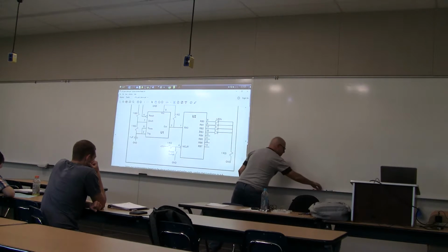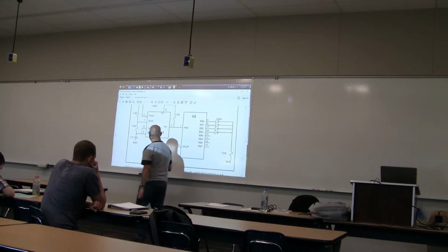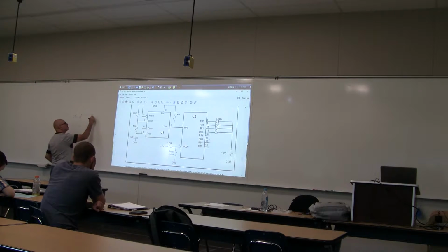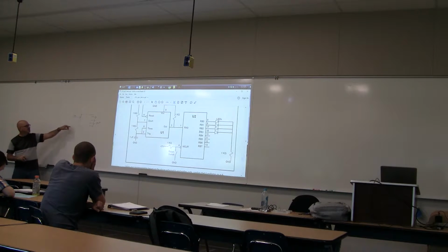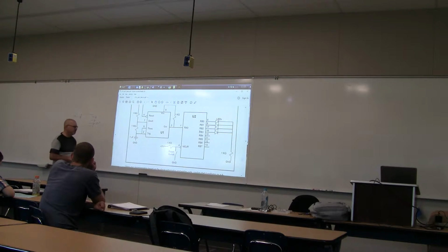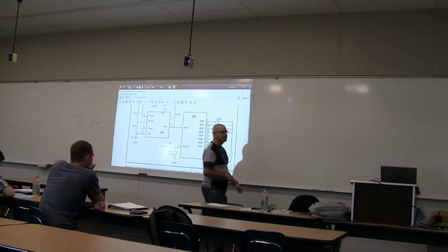So what does this circuit look like? Right, really simple system diagram. 1 input, 4 output lines. And each time that this changes either high or low, the value of this 4-bit output should increase. When it gets to all 1s and you tick once more, it goes back to 0 and keeps going. And it's all done through software.